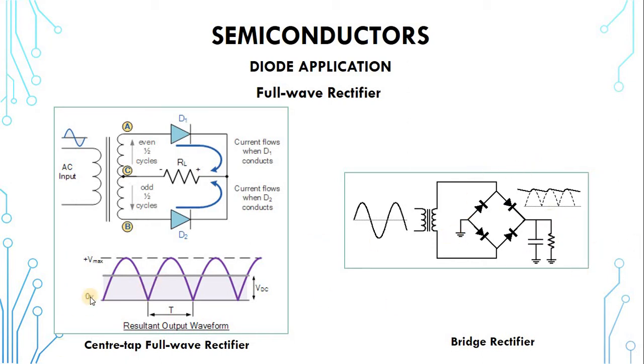Now remember that this is the kind of waveform with both the center tap wave rectifier and the bridge rectifier. This is a waveform they end up giving to the load, but the load needs a steady one. So what we need to do is to prevent this current from falling to zero. If it can stay at whatever level it is throughout time, that's what we want. But here it rises and then falls, rises and falls, rises and falls. So how can we prevent it from falling?